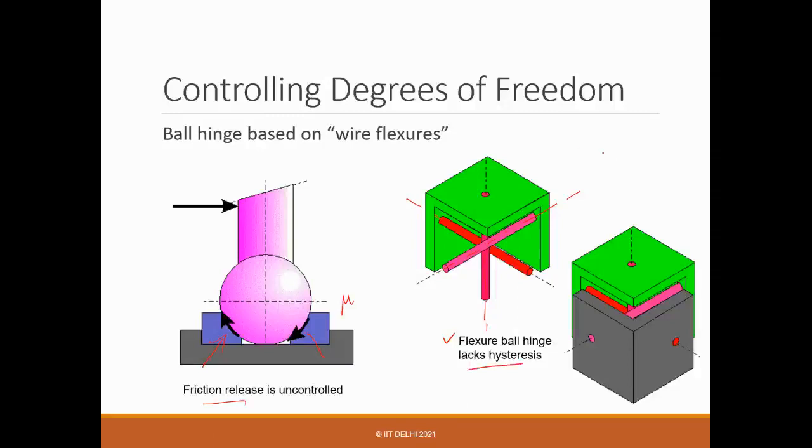So it's always F equal to Kx. So there will be some deformation, and it will be completely governed by this stiffness. So there will be some stiffness, and there is always one-to-one correspondence. Hysteresis is something like you don't know where you are, right? And whenever you have friction involved, you will have a dead band, and you are sure where you are.